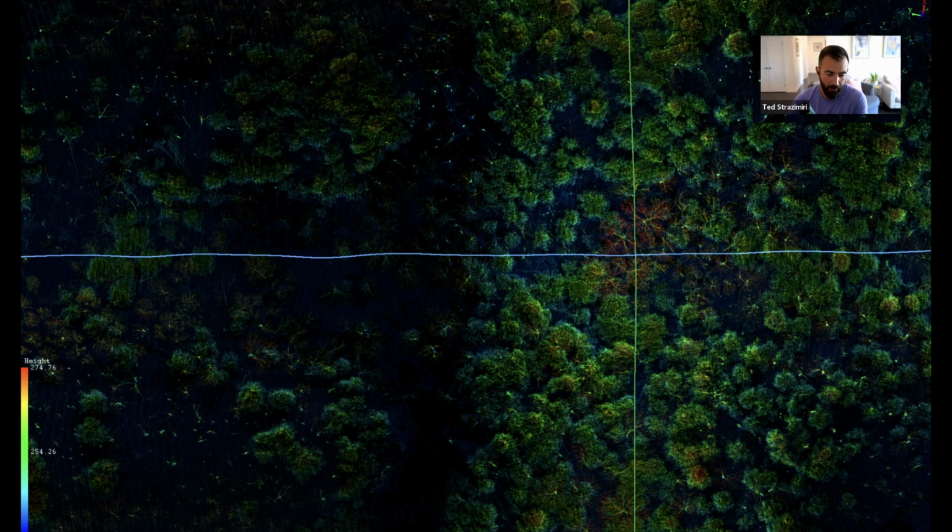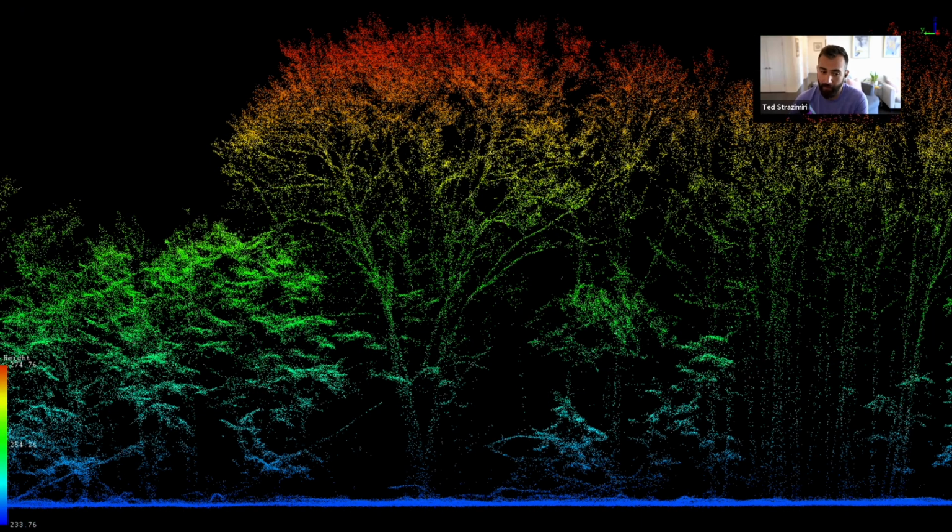And when you look specifically at those points that were generated from the trajectory, you can see the area where there is a cross between two flight lines. You can see that there's more points there, right? It's a lot brighter. I'm using the glass shader here to display this, so it is a little bit different than typical point cloud rendering, but it really brings out that difference of more density in that area where two flight lines intersected versus the blue line that came across. And when we look at the profile here, I'm switching between one line and two lines, so you can see the amount of points basically doubling as I go through this.